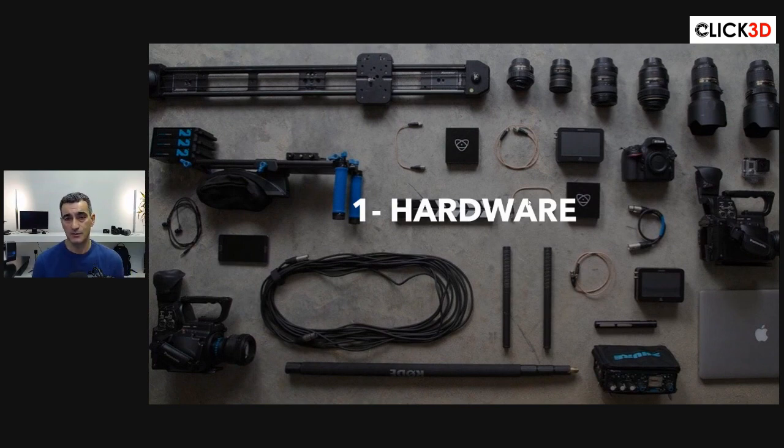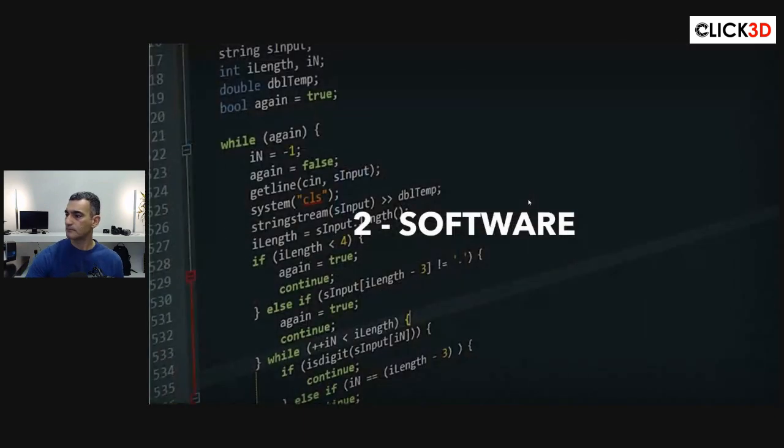So, for example, with laser scanning, you may want to use targets in some cases, or I should say, in some cases, you have no choice but to use targets. But often, you can get away without them. But certainly, the type of equipment that you have with a laser scanner is something very specific, whereas with photogrammetry, it's very general. And then from there, the world is your oyster, depending on how much money you want to throw at it in terms of what you want to buy for hardware.